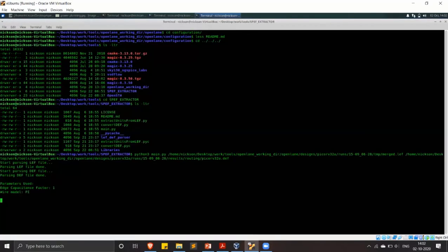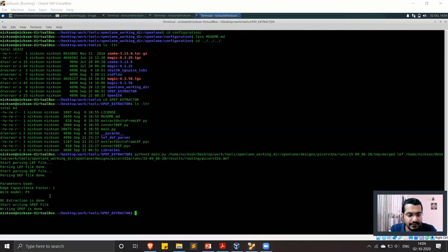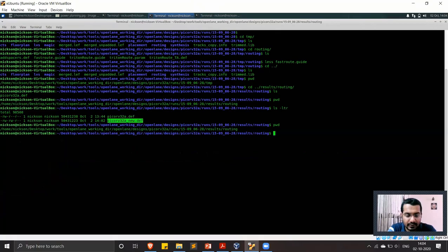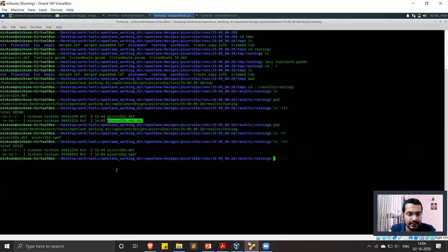So let's wait till this gets over. Yeah. So the spec generation, the extraction, has completed. We'll check the location. The location right now is results/routing. So if you do an ls -ltr here, you will see the spec file. So that is the spec file that got created.